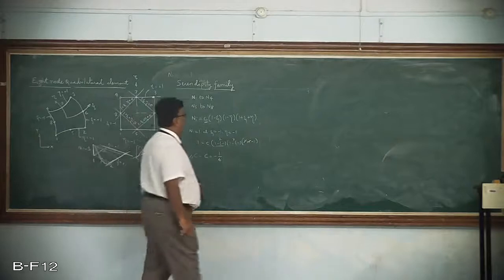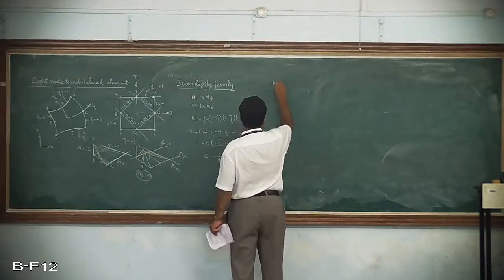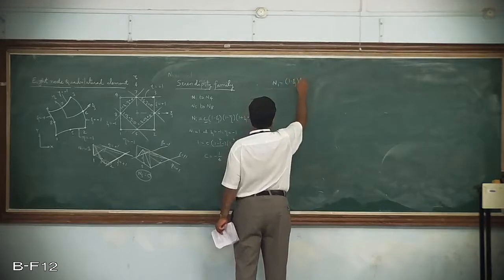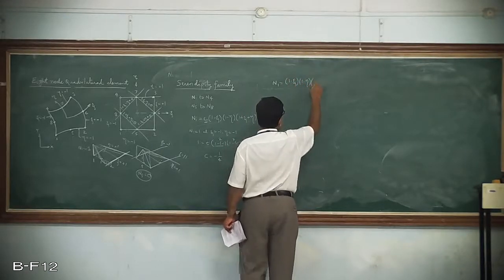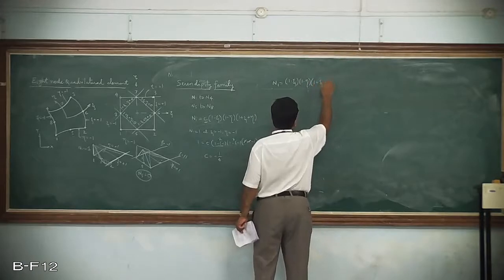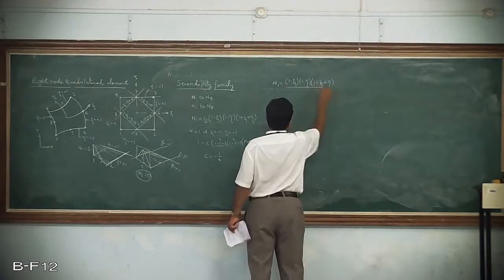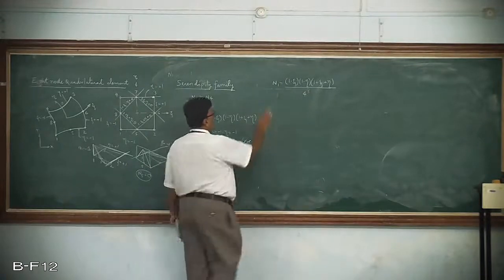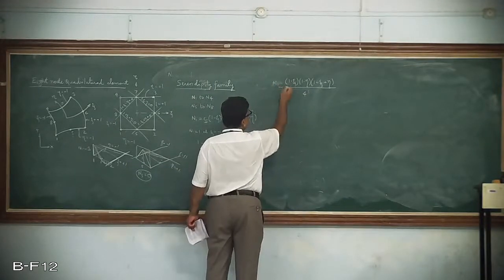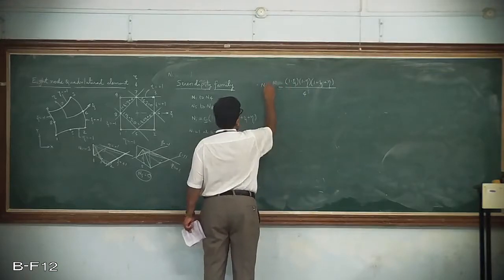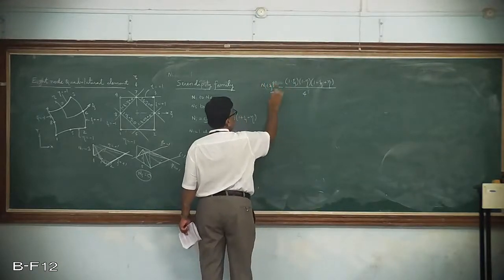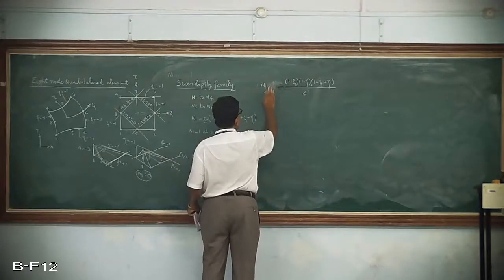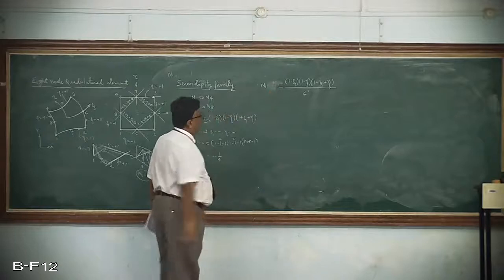So accordingly, my shape function n1 becomes 1 minus zeta, 1 minus eta, 1 plus zeta plus eta, with C being 1 by 4, of course all this with a negative sign, because C is minus 1 by 4. So n1, I call it not a function of zeta, it is n1 only, because n1 contains both zeta and eta terms.